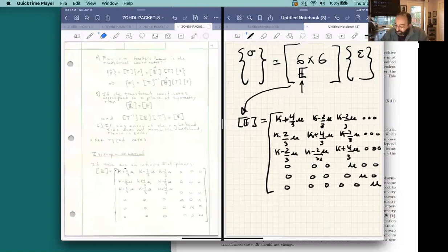Now, the nice thing about this is that every one of the components that exists inside this matrix equation actually can be represented by a combination of two parameters, kappa and mu. The reason that we have this kind of kooky decomposition is that those material constants have a very physical meaning.